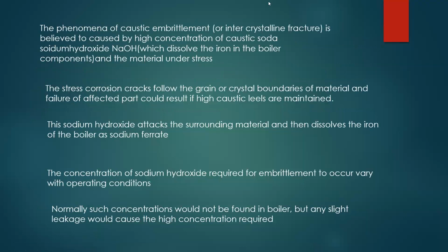Excess alkalinity of your boiler water. Okay, so the phenomenon of caustic embrittlement. Sometimes they ask like this only: embrittlement, caustic embrittlement. Intercrystalline fracture is believed to be caused by the high concentration of caustic soda, that is sodium hydroxide, which dissolves the iron in the boiler component and makes the material under stress. The stress corrosion crack will follow the grain.